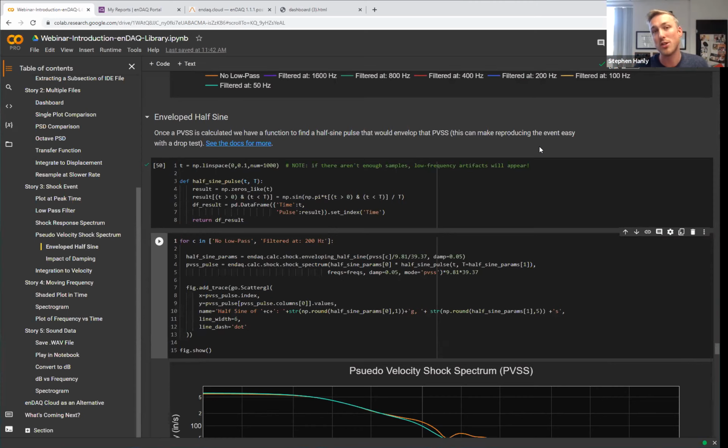Typically you're doing shock testing because you want to inform some design decisions. So you'll want to know, okay, I have the shock event, and it's really being amplified if I have a natural frequency in my system at 50 Hertz. So I have to avoid that, or I have to add in an isolator. You can't get any of that insight by just looking at peak-to-peak acceleration in the time domain. That's impacted by sampling rate.